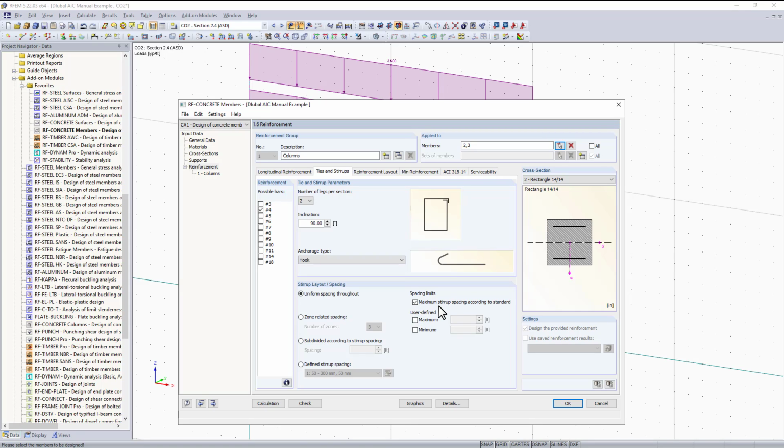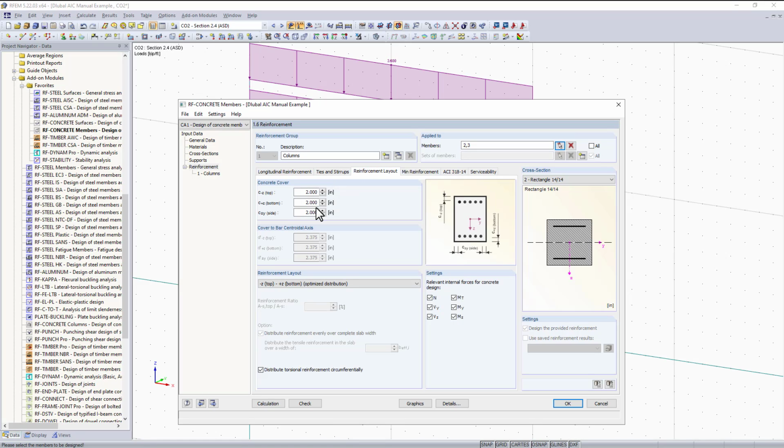Following that, we have our reinforcement layout, and the first thing to check is the concrete cover. The ACI standard refers to table 26.13.1 for concrete designation. In this table, it shows you if you're using number 5s or smaller, and this will tell you to use a 1.5 inch for the cover, which should be adequate. If the program comes up with larger bars, I would want to come back and adjust this.